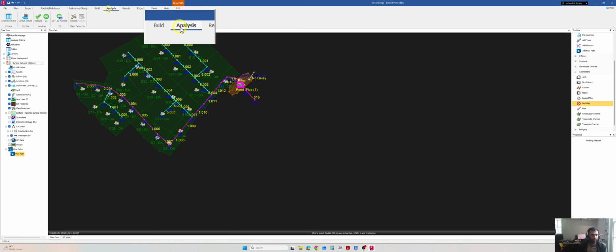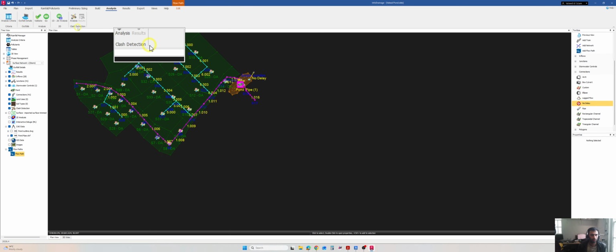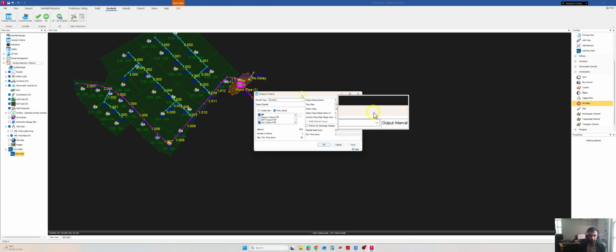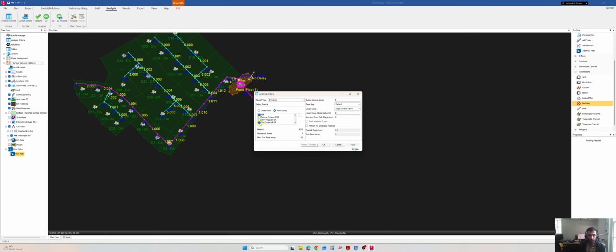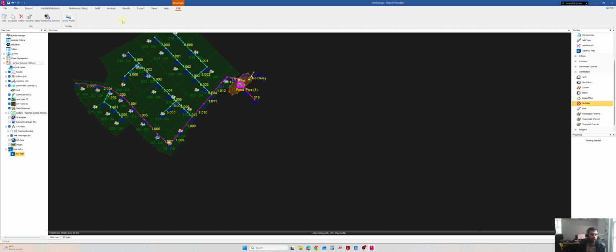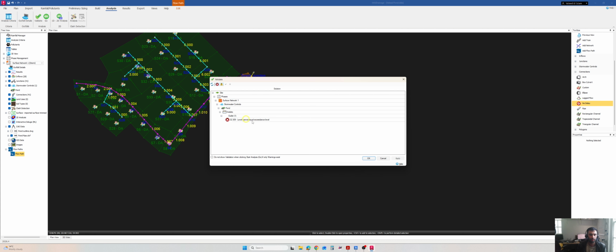Now I will go to the analysis, and to see my analysis settings, my rainfall criteria. So I will use this rainfall. Interval should be 2 because I'm designing a pond, so better calculation. Shortest distance. Again, the rainfall data, you can use your own rainfall data. I will click OK. Again, go to the analysis, validate.